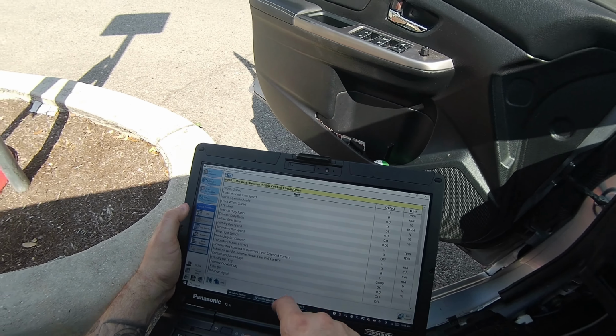So if you're not too sure what your PID is doing in freeze frame, then at least what you want to do is if you get 3 columns of freeze frame, you want to start looking for dropouts, because that dropout might be the breadcrumb trail you need to take you somewhere. So we're going to call this freeze frame a loss. Bummer. So let's see what's going on. What does a P0801 tell us with the OEM information?